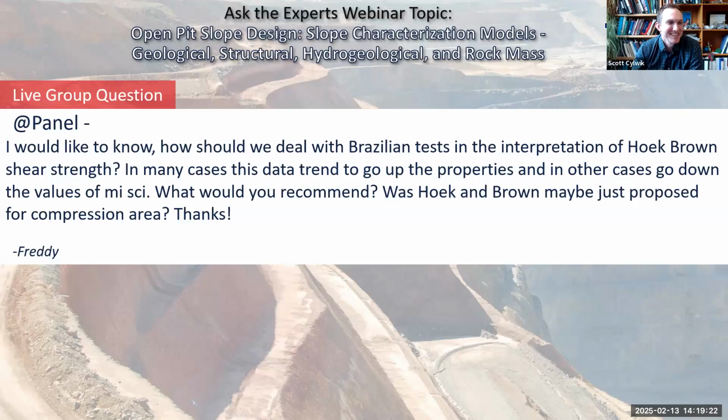Yeah, no, and thank you, it is a funny area. Just because I feel like in the old days, like the 80s, 90s, I think it was more common to try to use that Brazilian tensile data, so basically the measurements of the intact rock tensile strength, to try to fit your Hoek-Brown curve.